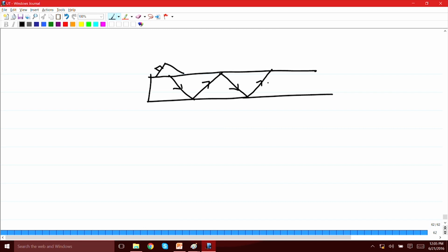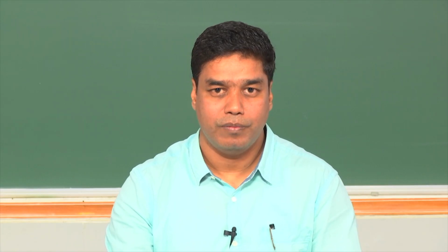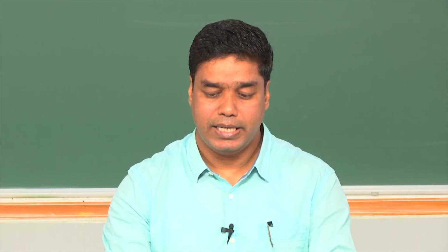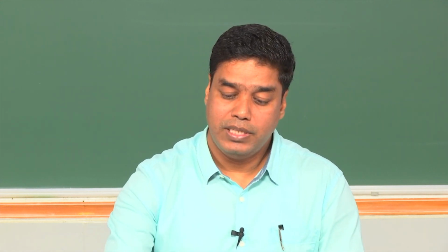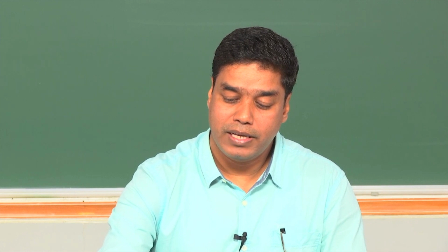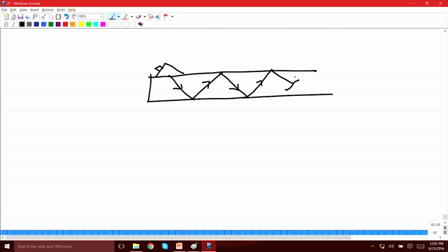Okay. So, that means that back wall echo that you see in case of a normal probe, you are not going to see that in this case. Okay. So, this echo will come back only when it encounters an interface which could be a discontinuity or a defect.